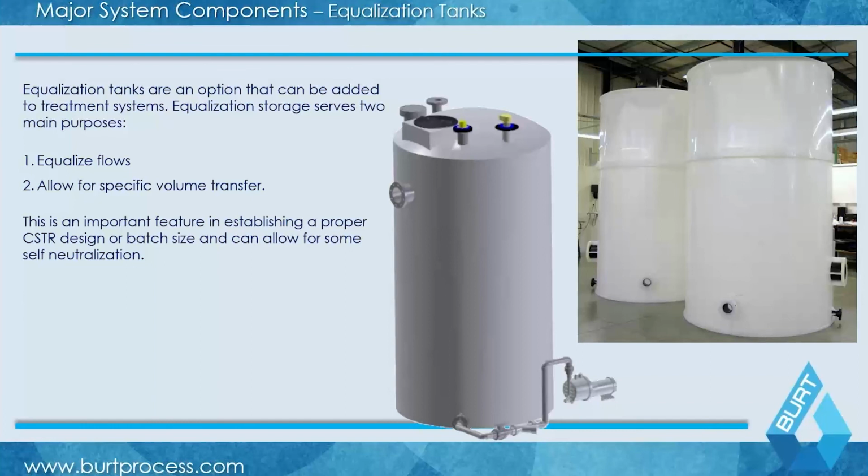In a batch situation, you absolutely need an EQ tank because now you're using that as your holding volume. So when you shut down your effluent, you can transfer that specific volume. So it operates in a very similar capacity between continuous flow and batch systems, but with a batch style system, your EQ tank is essentially becoming that reservoir. You can have those different surges in flow come into it at that point.